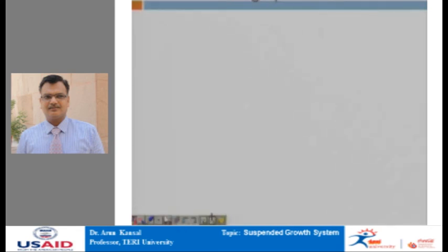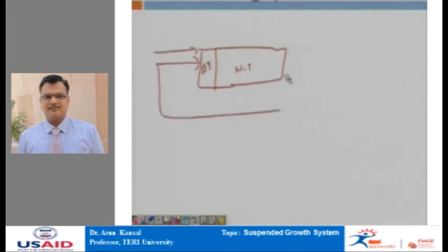So, the practical application for denitrification in the activated sludge process is somewhat different. Here what we do is we first provide a denitrification tank, that is, a normal aeration tank is converted into a denitrification tank initially, followed by a nitrification tank, which is a normal aeration tank. Wastewater is coming here, and the system operates the way it was discussed earlier.